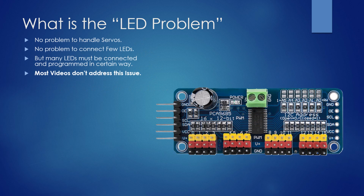Let us look at the PCA9685 connectors. SCL clock and SDA data are the only two connectors needed for the I2C bus, here marked green and orange. Then we have ground and VCC that power the PCA9685 internally, here marked black and red.